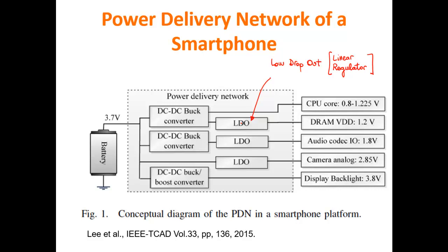As you probably know, the LDO, the linear regulator, provides a very nicely constant voltage, but with a relatively small power efficiency. And this is why you typically need a previous DC-DC buck converter, which is a switching converter that has a higher power efficiency, and then you use the LDO just to do the final tuning of the voltage.